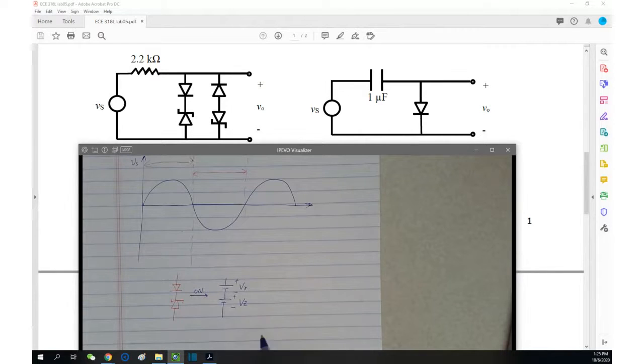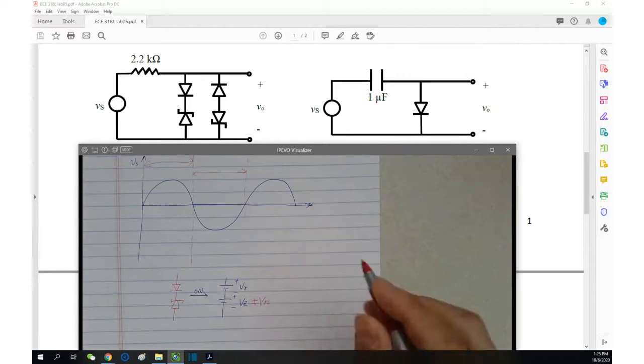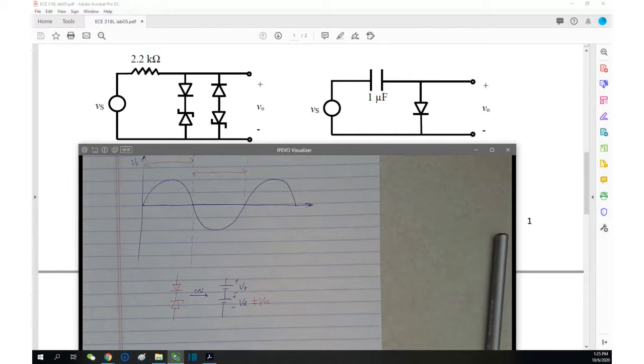The VZ is the breakdown voltage, which is designed to be smaller than normal, so that you can use the zener to protect the circuit and so on and so forth. So this VZ is not V gamma of the zener, okay? These two are not the same thing. Breakdown voltage, remember, is the reverse biased voltage. That's why the model is like this.